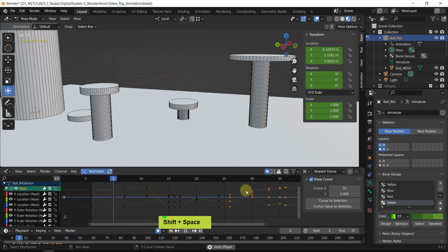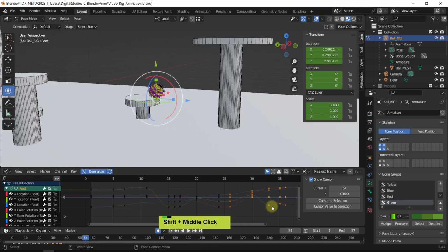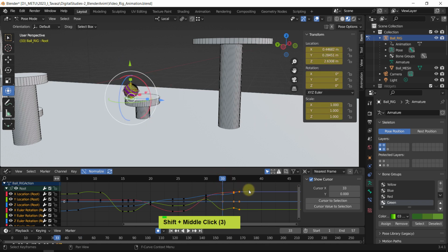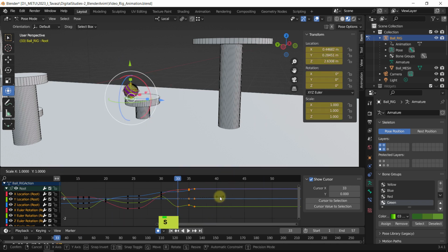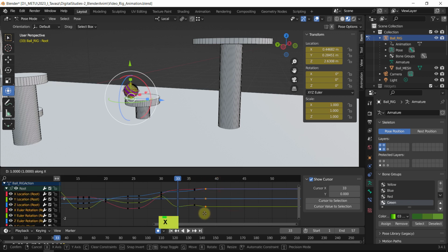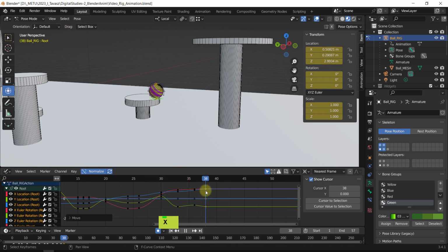So jump. And it's pretty fast, so I will just select these keys and make the keyframe here and scale on the x-axis and just scale it out. Maybe this one, just G and move slightly, and that's slowing down the whole thing. All right, so let me see that.